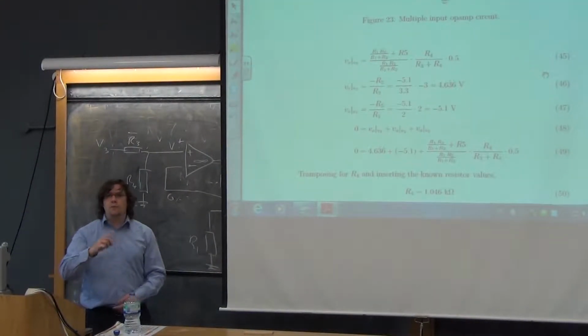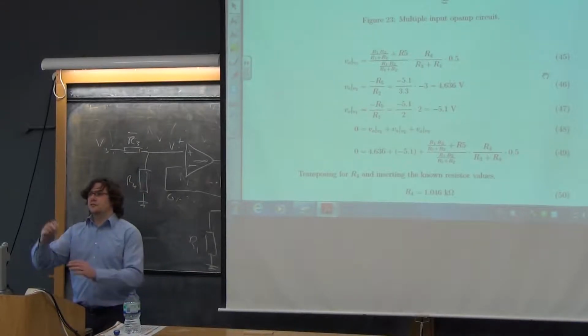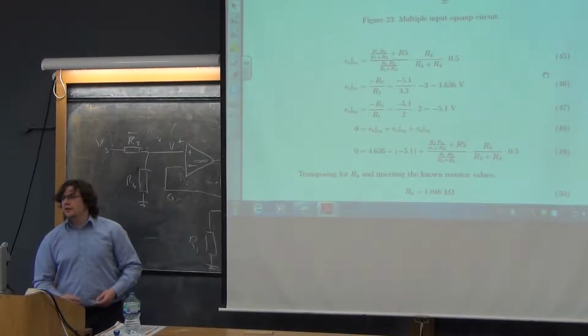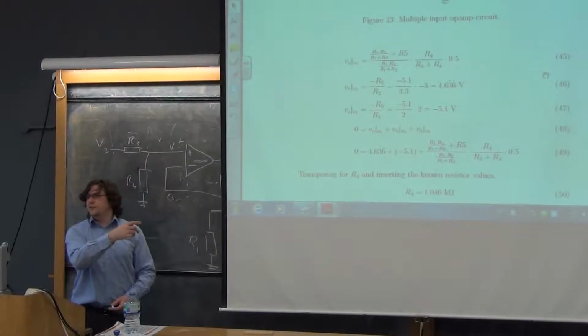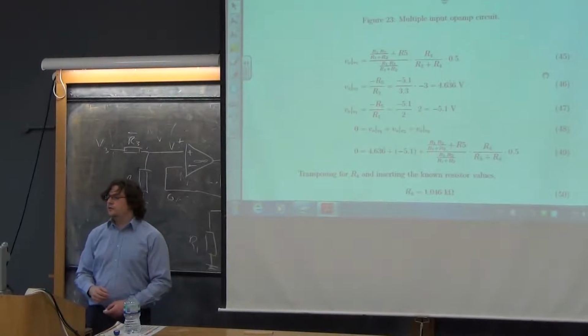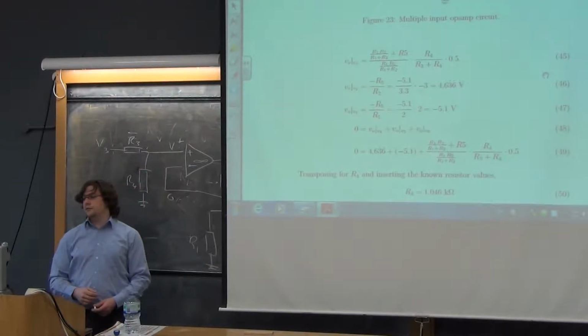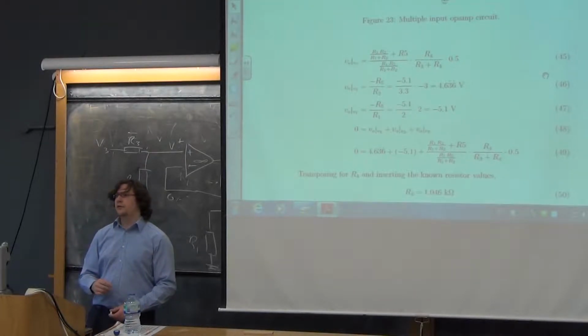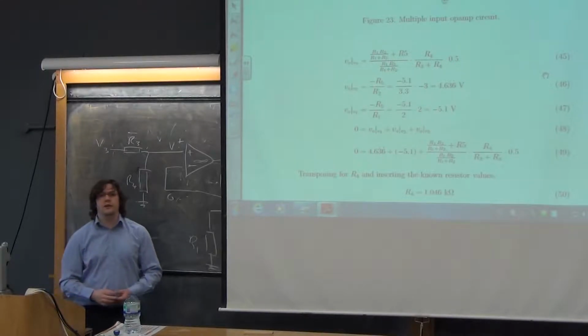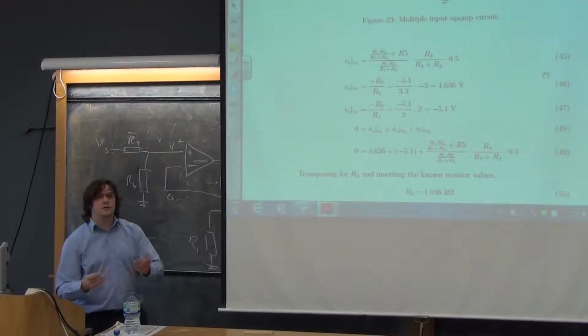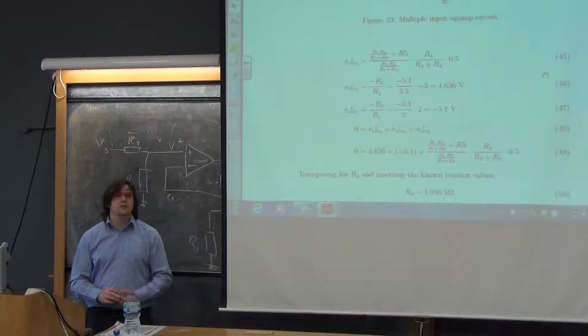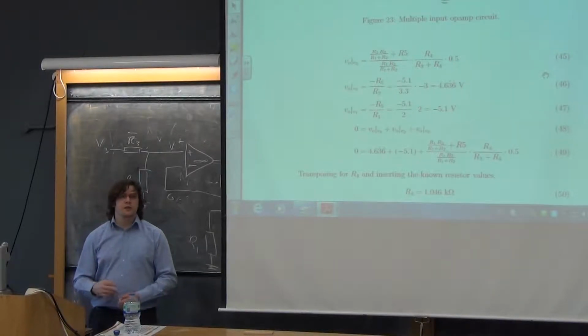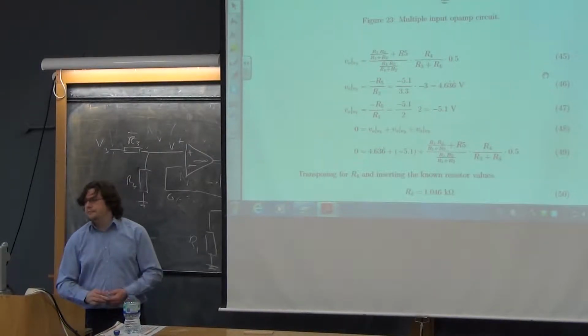If you don't like doing one big one plus a fraction, you can do it as the bit to ground plus the feedback over the bit to ground. But if you were to divide through by the R5 at this point, you'd get the other form. So there are two ways of doing it. It's the same equation, you're just dividing through by one of the terms. And sometimes you'll see it in a textbook written out slightly differently, but it's all the same.